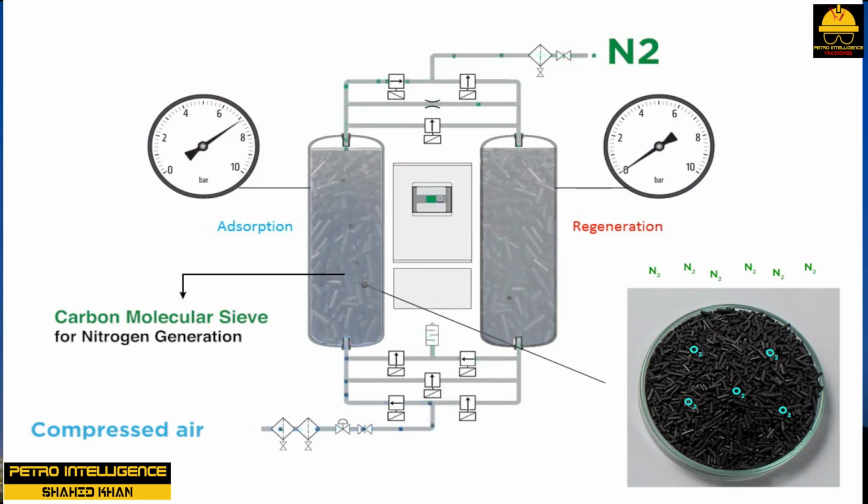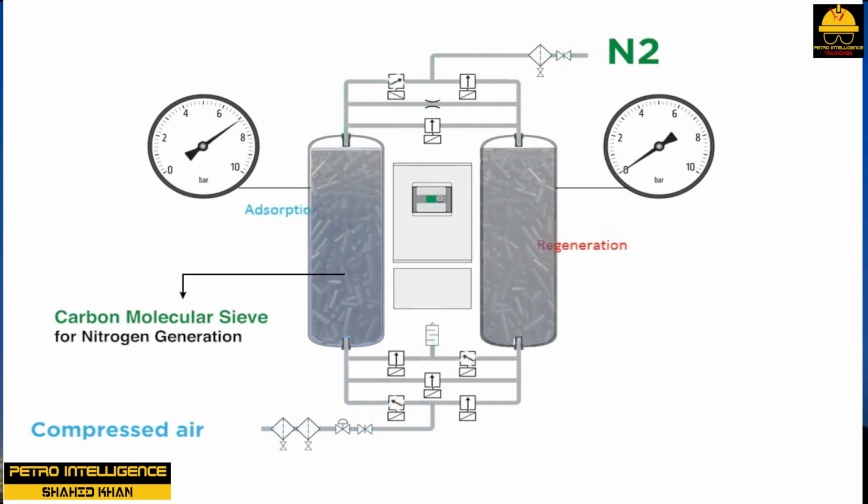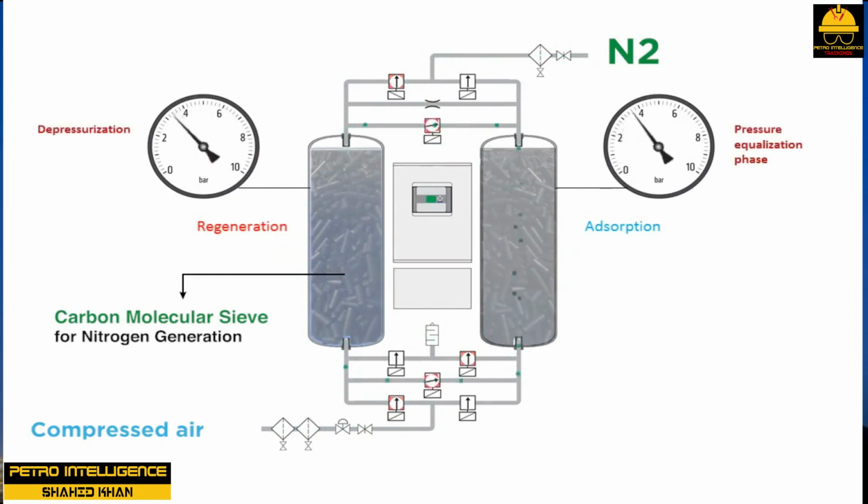During the adsorption process, the mixture to be separated is passed over the fixed bed medium, adsorbent, in the primary device. At the conclusion of the cycle, the process flow is transferred to the secondary device. A stripping gas is admitted into the primary device. The stripping gas is designed to remove or separate the selected chemical from the adsorption material. At the conclusion of this cycle, the stripping gas stops as the process switches back and repeats the process.